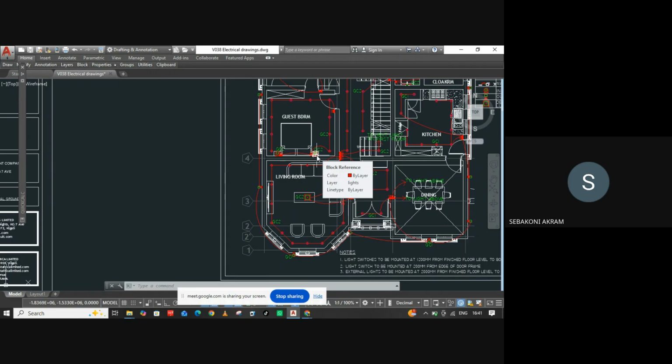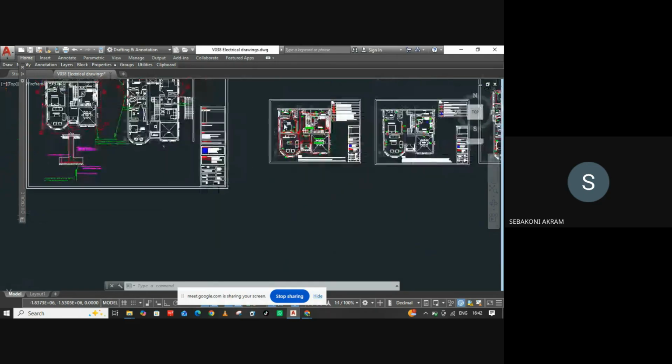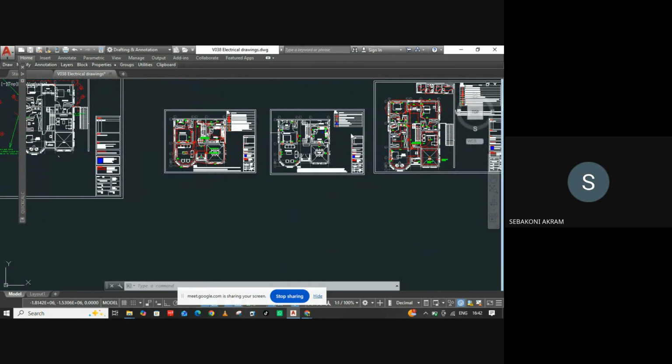Considering inrush currents, which I remember telling you to read about, the product data sheets specify all those things. Assuming an inrush current of about 10 times the current, that gives you about 10 amps. Are we together on that point? So you've identified that is 10 amps of load for that circuit.